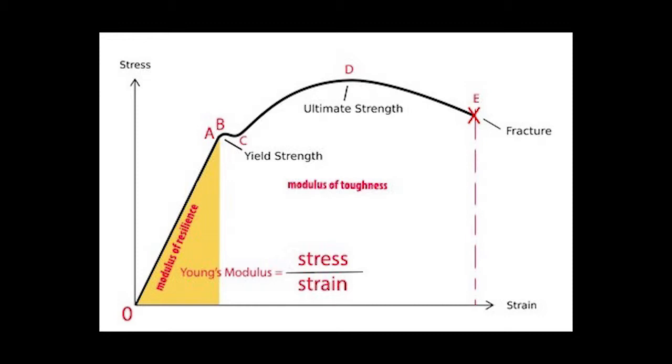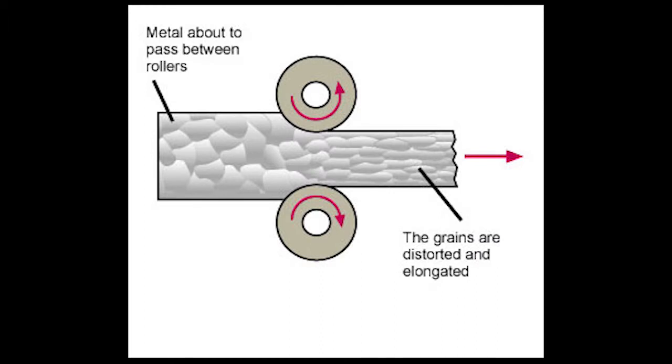To reiterate, once the material selection process is complete, the manufacturing process would be as follows. First, the 1045 carbon steel would undergo strain hardening to increase the overall strength of the metal to yield a greater safety factor. In this process, a stress greater than the yield strength would be applied to the sample, causing dislocations to move and additional dislocations to form. The tendency for dislocations to get tangled or pinned with one another increases as more form, which also decreases their mobility and leads to a stronger material. This type of strain hardening is called cold working, as the atoms are unable to rearrange themselves at lower temperatures.